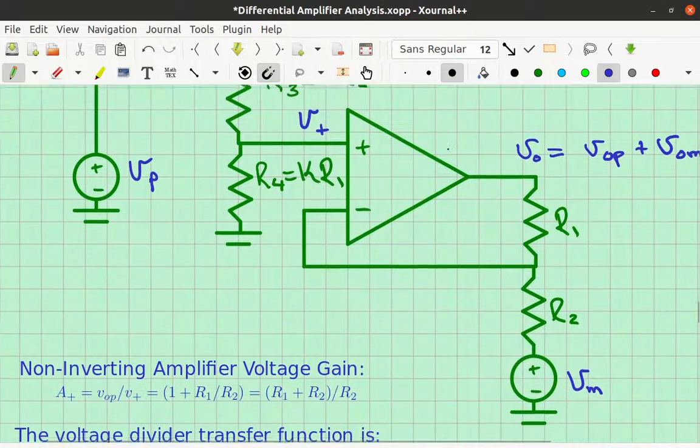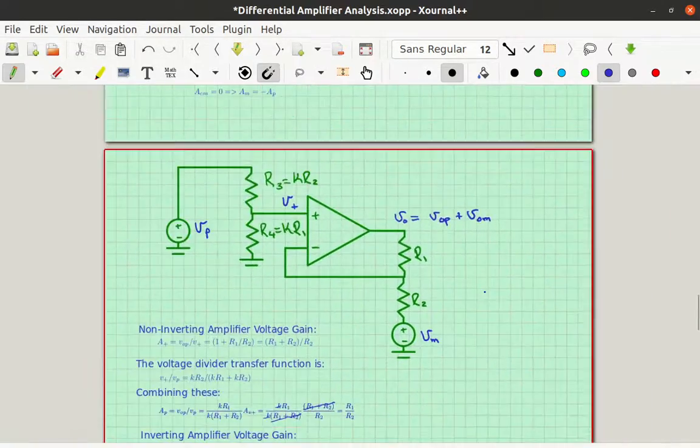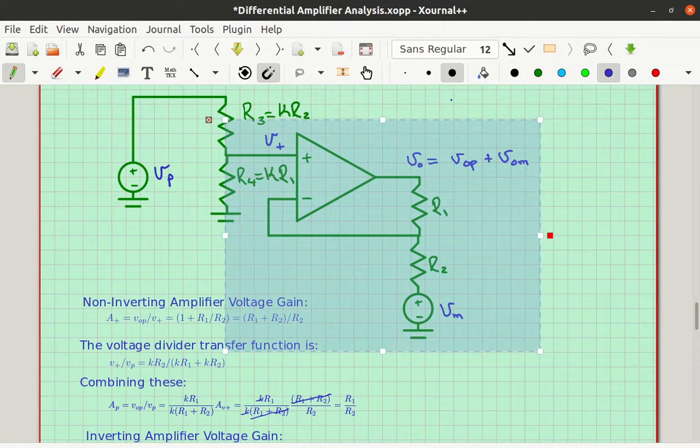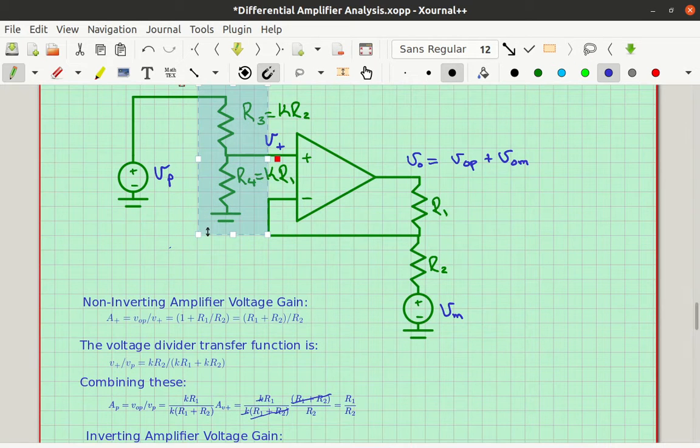So here's how we're gonna do this thing. We're gonna take the circuit that we had before, which was essentially this part right here. We're gonna add this voltage divider right here, and that will turn down the gain of the non-inverting amplifier to be equal to the gain of the inverting amplifier, only upside down, just with that minus sign that we just saw we needed.